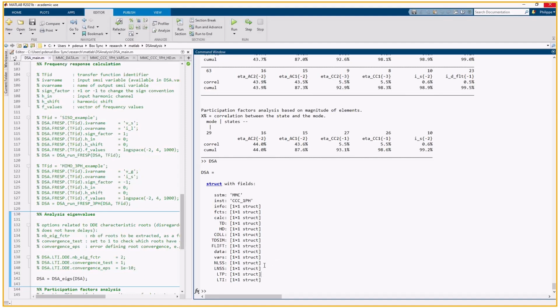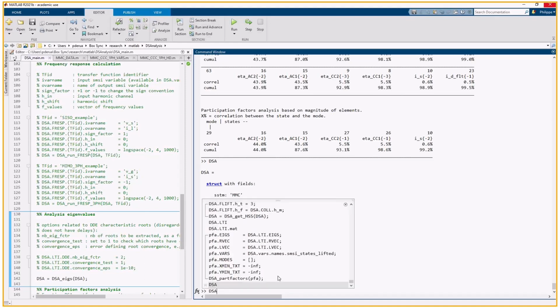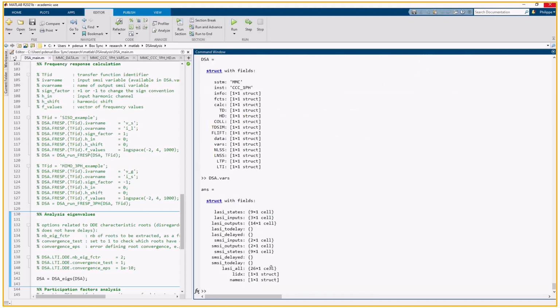Here I would like to have frequency responses. So I would like to know from which inputs to which outputs I can calculate a frequency response. This is something that I can find in the variables list. There we are. So again, I know that I have now linearized the system, so I will be working with small signal inputs and small signal outputs.